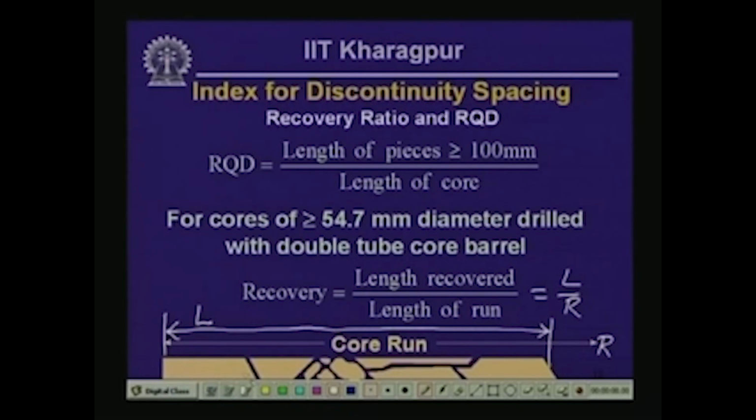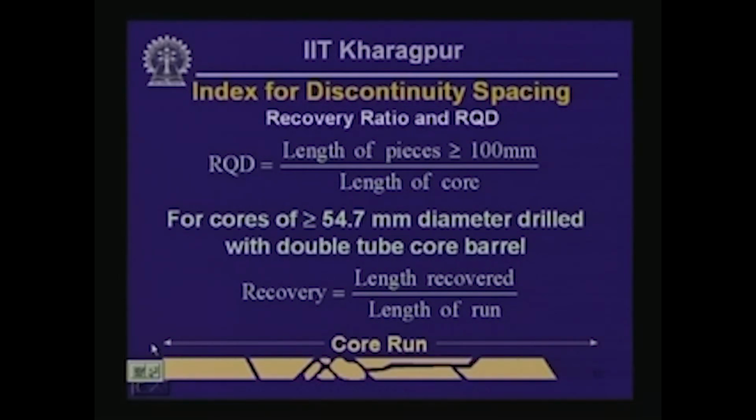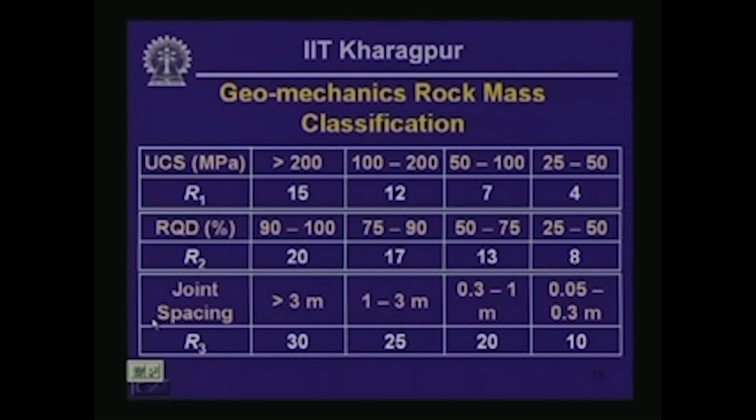So, both RQD and recovery, if you recall, when we discussed the logging activity of subsurface investigation, both RQD and recovery are details that need to be included in the log that describes the drilling process, and they are evaluated at the time of the drilling itself. Okay. Now, we will try to get into the geomechanics classification of rock mass.